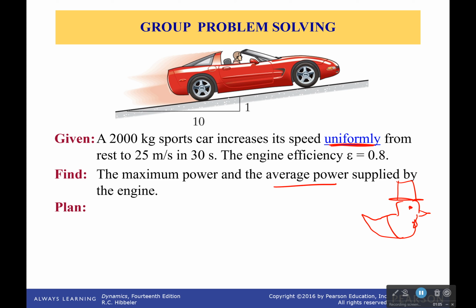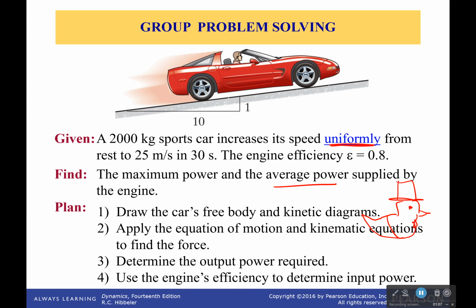So, what's your plan? Well, your plan is this. Draw the car's free body and kinetic diagrams. Apply the equations of motion and kinematic equations to find the force. Determine the output power required, and then use the energy efficiency to determine input power. Okay, now with that in mind, pause, go try it out.